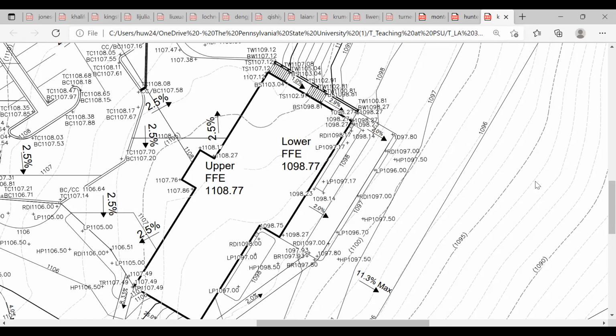In reality, because the site has a lot of room, we wouldn't necessarily choose to build a bioretention planter right next to the building edge. This sort of planter is more applicable in a very dense area where you don't have anywhere else to put that facility. The reason being, it wouldn't be able to infiltrate close to a building foundation. So that facility will be lined anyway.